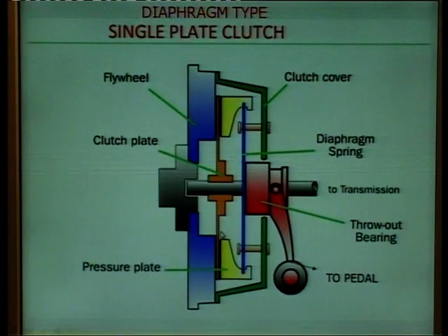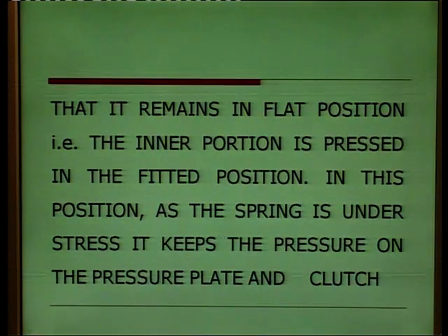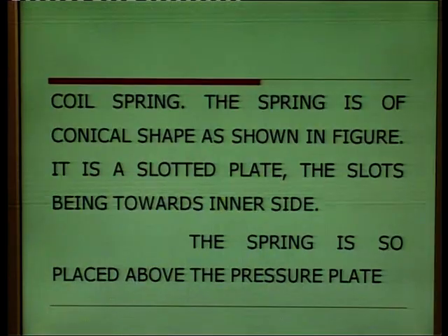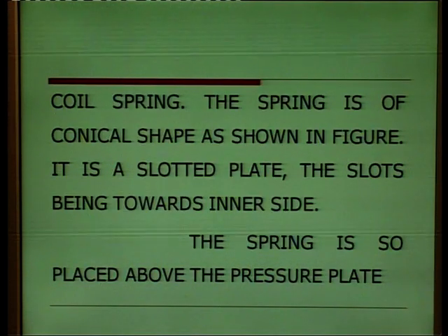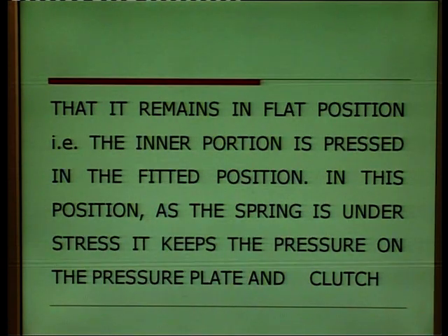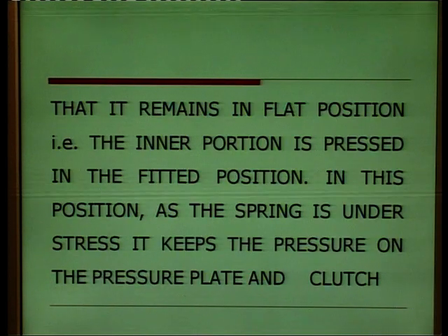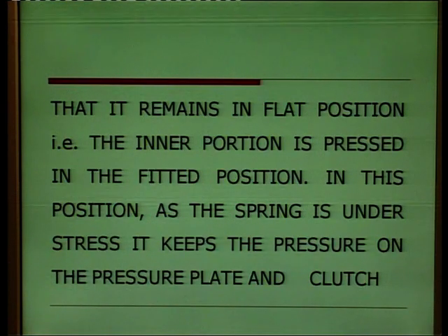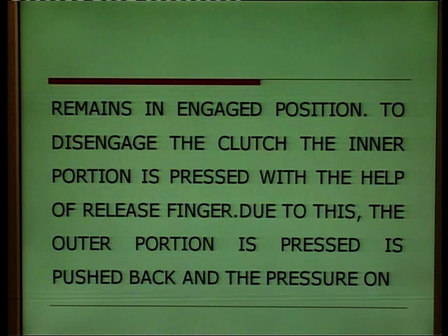Then continue. The spring is so placed above the pressure plate that it remains in flat position, i.e. the inner portion is pressed in the fitted position. In this position, as the spring is under stress, it keeps the pressure on the pressure plate and the clutch remains in engaged position. To disengage the clutch, the inner portion is pressed,